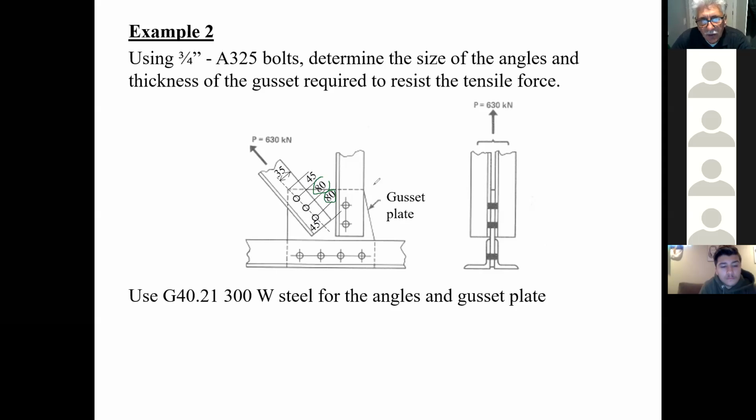Here, I know that when I put this gusset plate, it's going to be sized on my geometry, so I'm not too worried about it. Here I have my end distance from my bolt to my gusset plate, and here I have my end distance from the bolt to the angle. Here I do respect the 2.7 times the bolt diameter, because 2.7 times 19 is about 53.